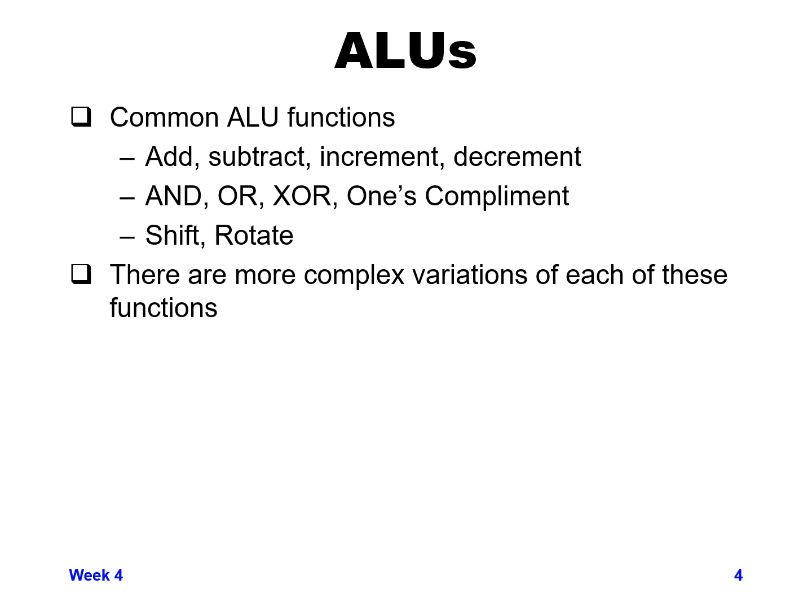So you can either perform the AND or an OR or an XOR function bitwise on A versus B, or a ones complement would be taking either the value of A or the value of B and inverting it, so bitwise inversion, 1 to 0 or 0 to 1. Those are kind of the bitwise types of functions that ALUs can do.